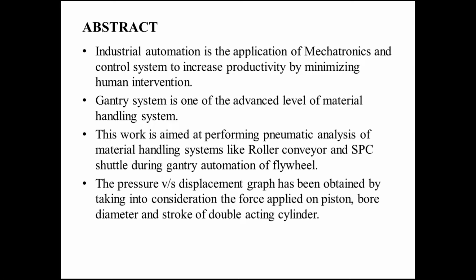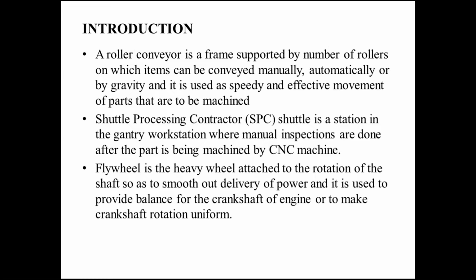The pressure versus displacement graph has been obtained by taking into consideration the force applied on the piston, bore diameter, and stroke of the double acting cylinder. A roller conveyor is supported by a number of rollers on which the material is conveyed manually, automatically, or by gravity. In our project, at input and output, a roller conveyor is used to move the flywheel and perform the gantry operations for loading and unloading of parts.